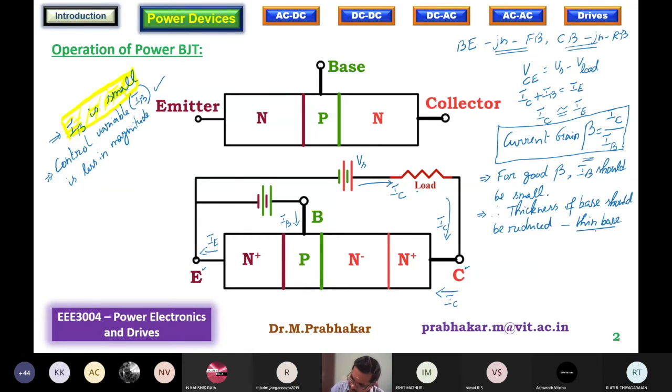This is preferred. Now you look at this structure. I hope you can see the arrow mark, or I will use a laser pointer rather. If you have a thin base layer, what will happen to the depletion layer? Where will the depletion layer grow, under reverse bias condition of course? Under reverse bias condition, the depletion layer has to penetrate into this n minus n plus interface.